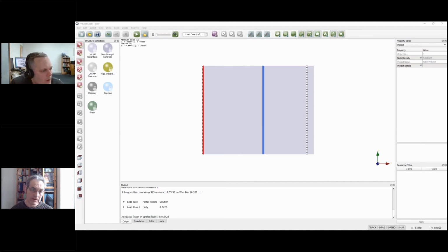Oh yeah, Matthew, you can jump in. I mean, if we had a bit more time, we could have talked more about it, but it is very much for flexural failure of slabs. It doesn't tell you anything about punching shear. It doesn't tell you anything about deformations prior to collapse either.